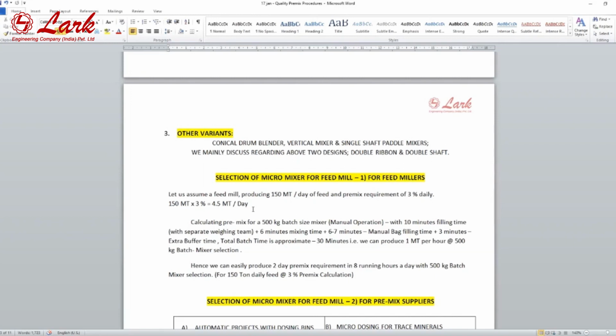VFD is a very good application in the hammer mill that we can use with respect to the grains and all other. I think only with the help of VFD you can control the particle size. Yes, sir, otherwise in a normal feed mill the RPM is decided by the motor or the pulley, and you cannot easily vary it. But for example, now when I'm making 5 feeds, if I need 5 different RPMs for the particle size, I will not invest in 5 machines.